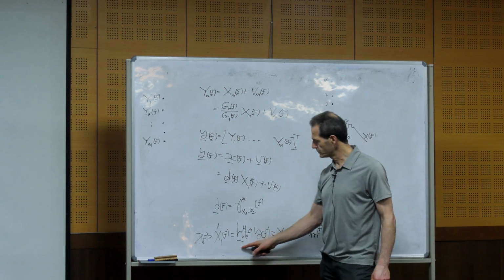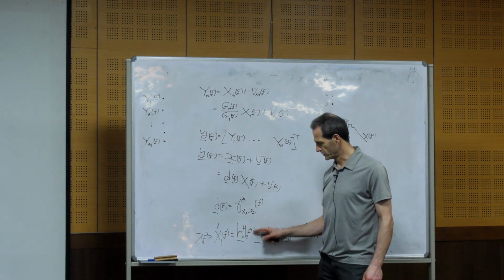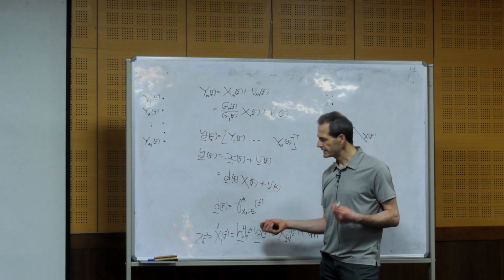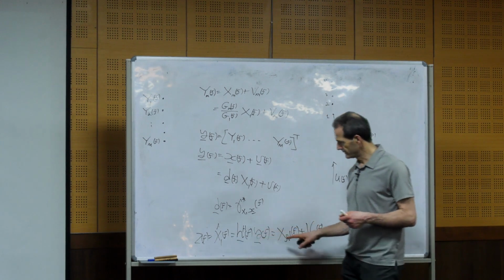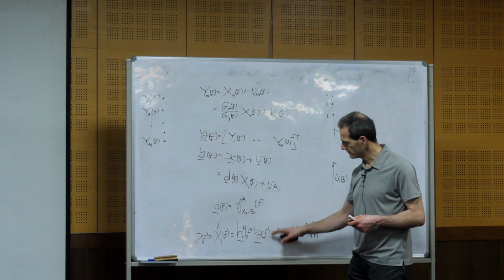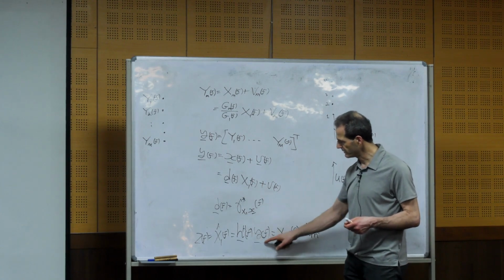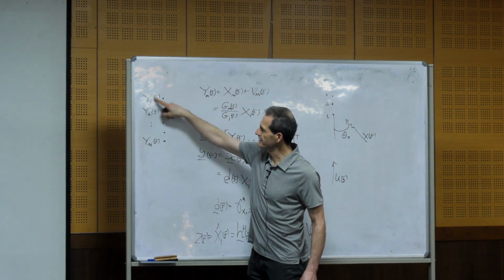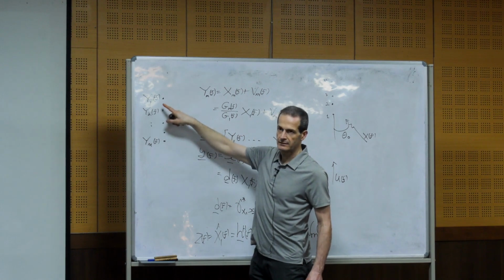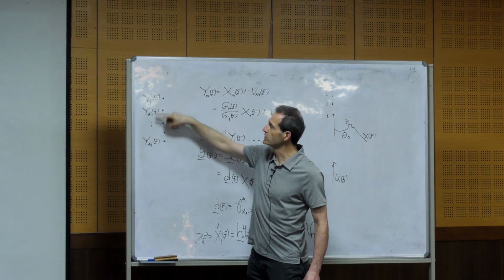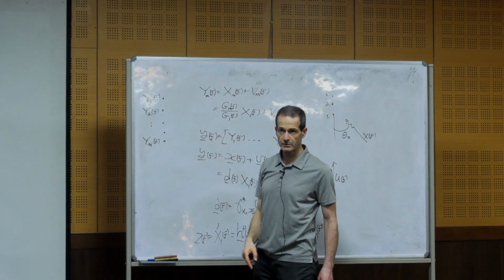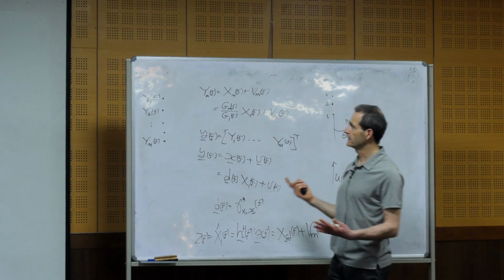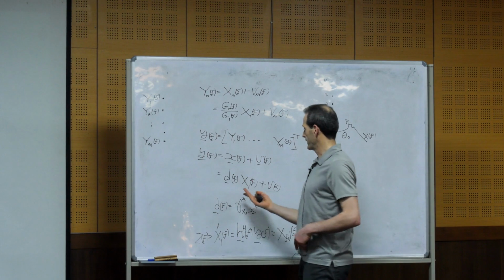If I try to find the optimal filter, you see that it takes into account the correlation within this vector. What does it mean, correlation between these vectors? Correlation between any two desired components in this vector, and correlation between any noise components in these two vectors, which depend on the configuration of the array and so on.